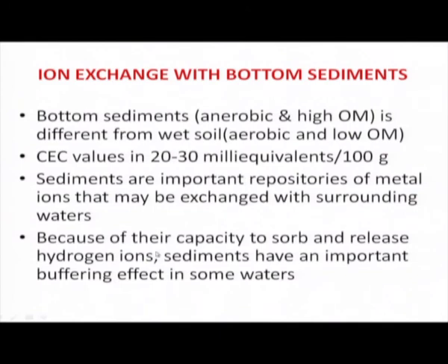Because of their capacity to absorb and release hydrogen ions, sediments have an important buffering capacity in water. The H plus ions released from the sediments act as a kind of buffer. Not only this, ion exchange reactions in buffering the water system are also very, very important.